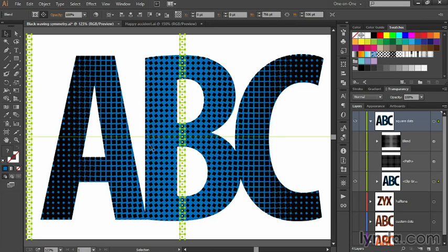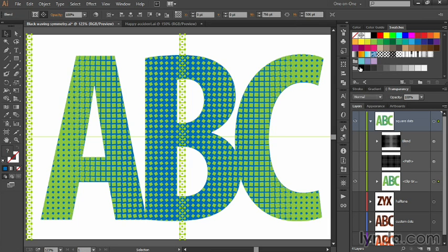And now I'm going to switch the colors around a little bit. I'm going to change the color of the blend from the Swatches panel to the shade of chartreuse right here, which is included with this basic RGB document. And its values are R140, G198, and B63 in order to infuse the square dots with a completely different color.